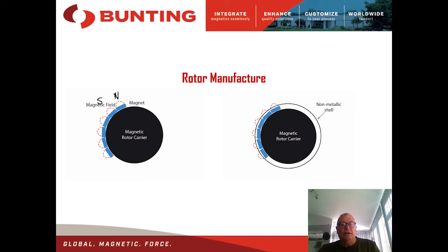Now, depending on the magnet depth and the magnet width will determine how far that magnetic field is kicked out onto the belt surface and how many poles that the particle will see as it passes over. So again, the more poles that the particle sees, up to a maximum, will define how far the particle is thrown, or how small a particle we can capture on the eddy current separator.